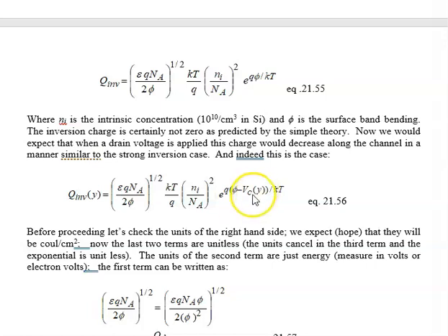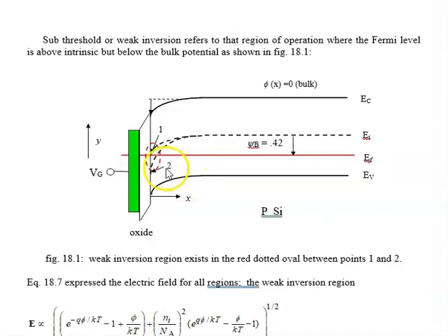Okay, but we do need the channel voltage, and here we have the inversion charge, which says that as channel voltage increases, the inversion charge decreases, because the band bending becomes less and less as we move along the channel. Now, we don't show the channel here. It is in and out of the paper. So we'd have to have a third dimension going out with the source and going in with the drain.